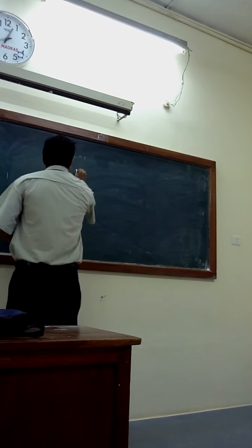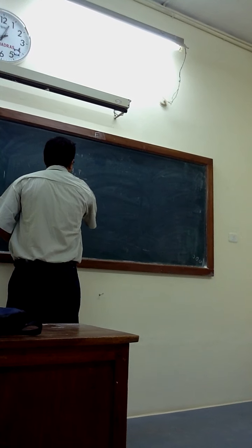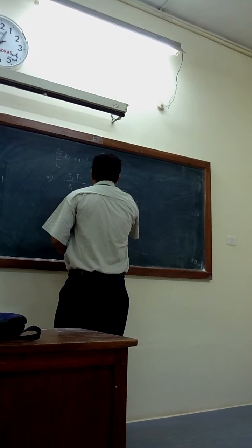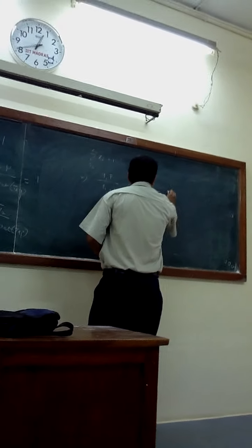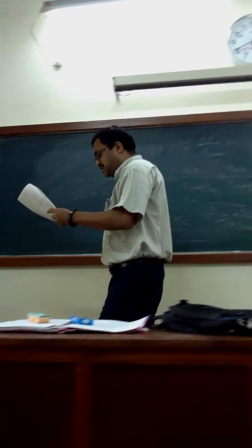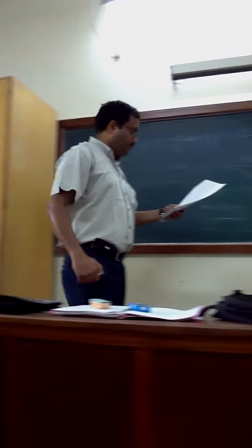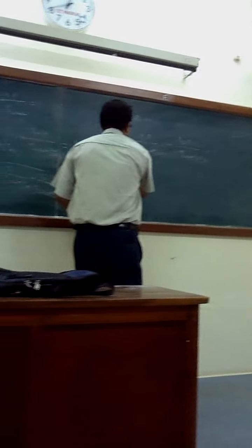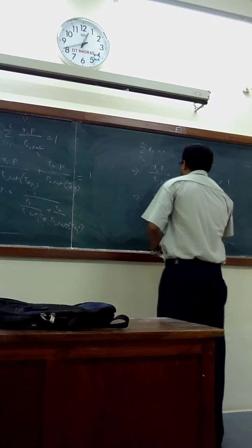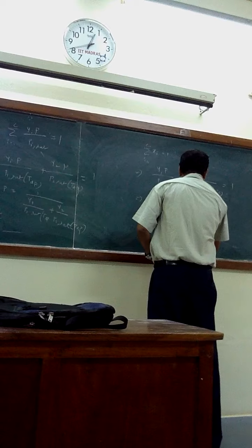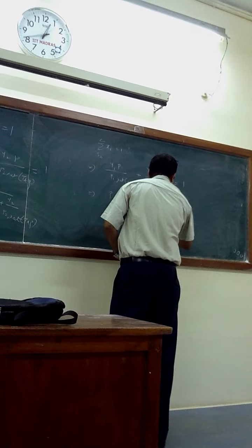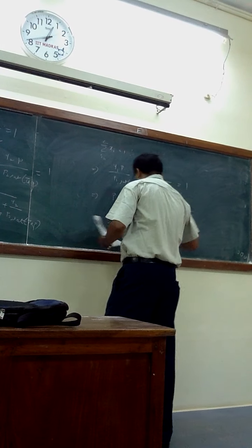So it is y1P by p1 sat at 80 degrees centigrade plus y2P by p2 sat at 80 degrees centigrade equals 1. Calculate p1 sat and p2 sat at 80 degrees centigrade from the Antoine equation and get the pressure. Pressure is unknown, so P equals 1 by (y1 by p1 sat at 80 degrees centigrade plus y2 by p2 sat at 80 degrees centigrade).